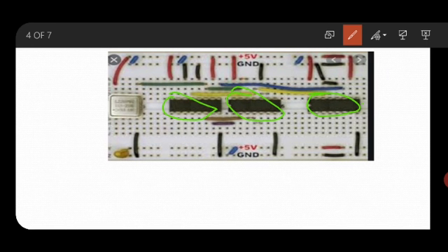The most used, very essential point for the circuit diagram is your VCC and the ground, because most of the components have to go to the ground. So a convenient way is that the top row, the row above, will be used for the ground connection, and the below one you can use for VCC, or vice versa. It is not mandatory that you use it like this.